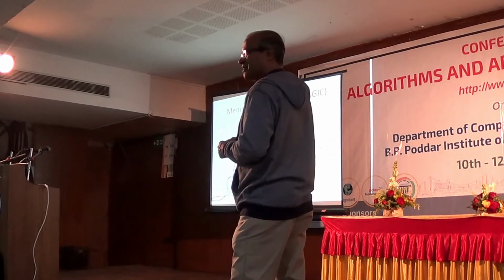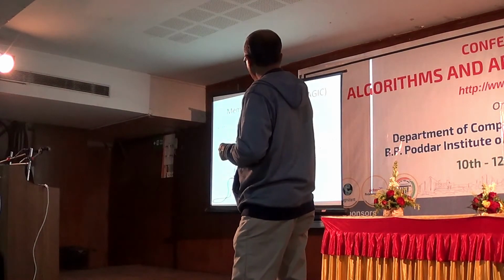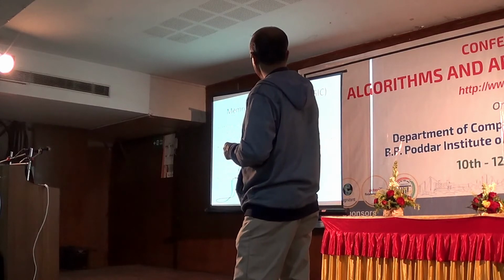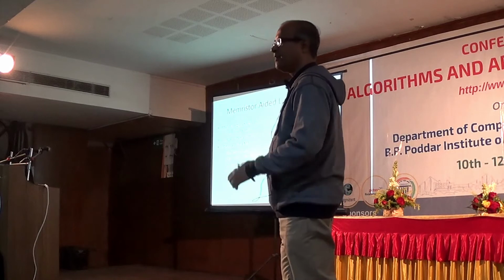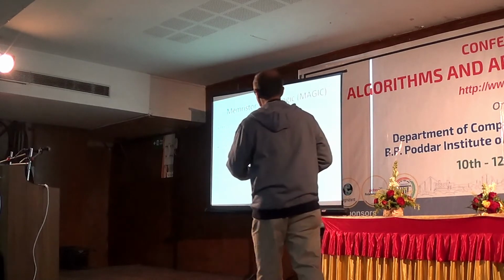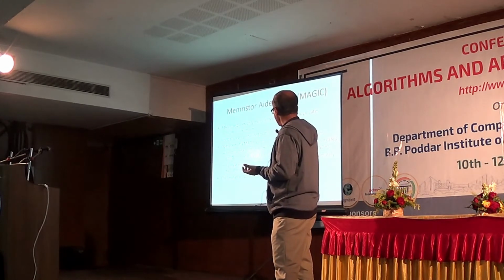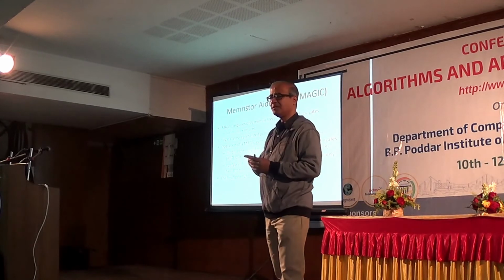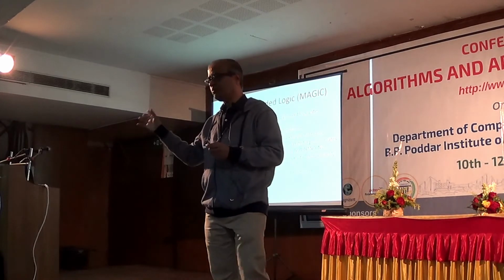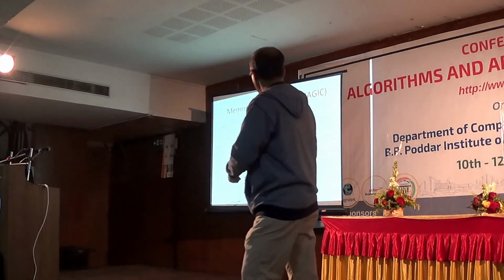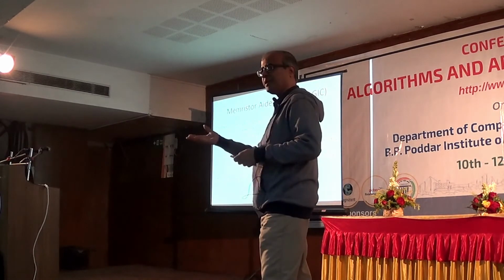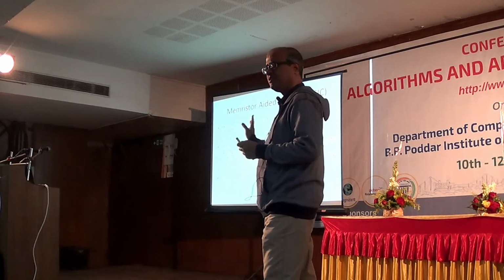And just like your imply, logic states are all again represented as memristor resistances. And here, to evaluate a gate, there are two steps to be followed. First, the output memristor is initialized to some state. Second, we are applying a certain operating voltage in the input. I shall show.